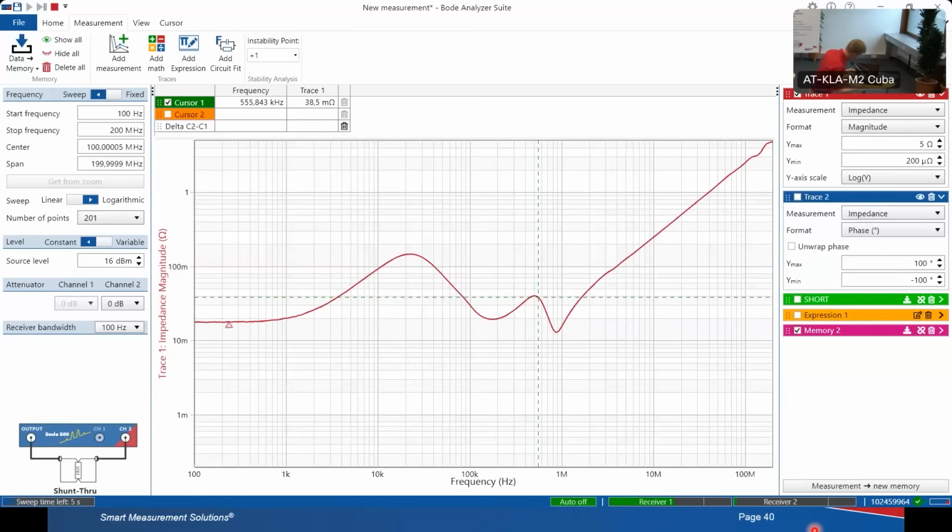Now I will change to a compensator with low phase margin by removing a jumper and placing the jumper again. So now the phase margin of the control loop has exactly the same crossover frequency, but a lower phase margin that causes the first peak to rise.